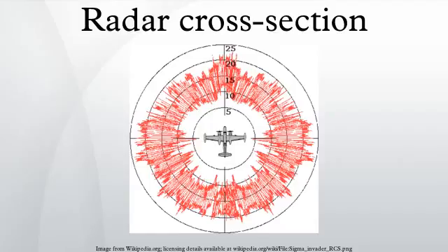Measurement of a target's RCS is performed at a radar reflectivity range or scattering range. The first type of range is an outdoor range where the target is positioned on a specially shaped low RCS pylon some distance downrange from the transmitters. Such a range eliminates the need for placing radar absorbers behind the target, however multi-path interactions with the ground must be mitigated. An anechoic chamber is also commonly used.